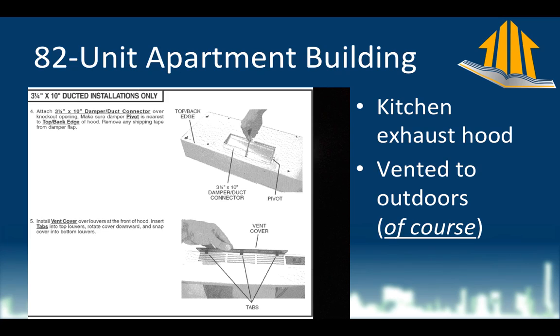We'd have condensation issues, all kinds of comfort issues in the kitchen. We would have mold forming. It would just be awful. So we need to uninstall all of these, reinstall with the backdraft damper. That means that they're going to be slightly lower. We got to cut all the caulk away and so on. So it was a big, nasty thing that happened, and that was before any actual diagnostics happened.